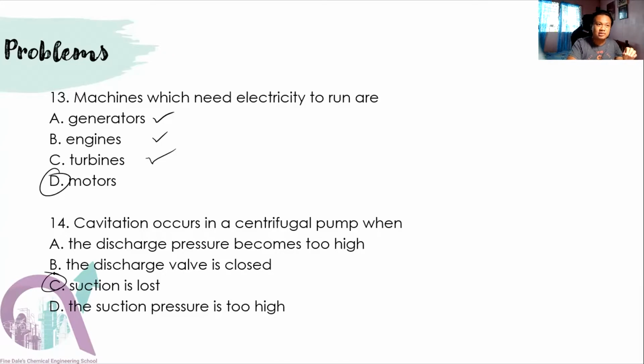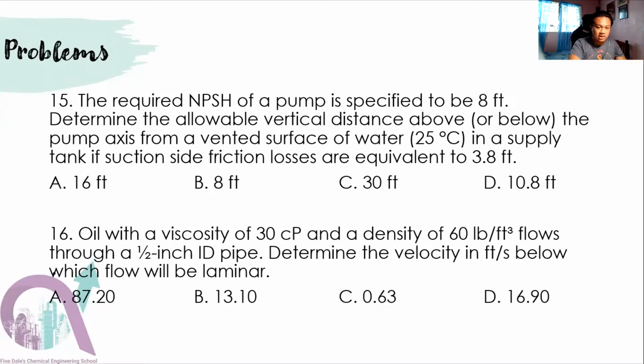So it is induced by this low pressure, meaning the water in the pump will boil. That will damage your pump, because I've heard cavitation in our experiments, and it's really noisy. Okay? So the required NPSH of a pump is specified to be 8 feet.